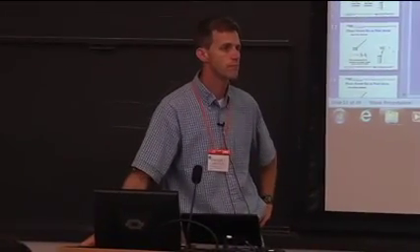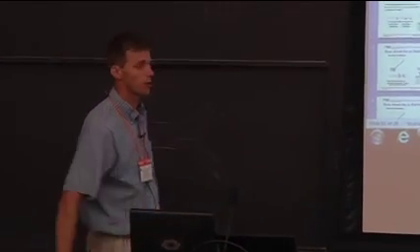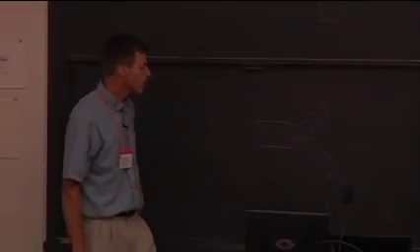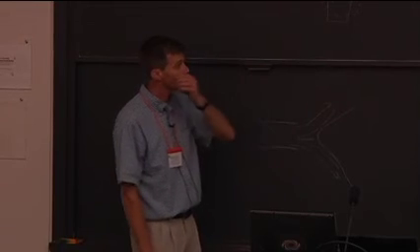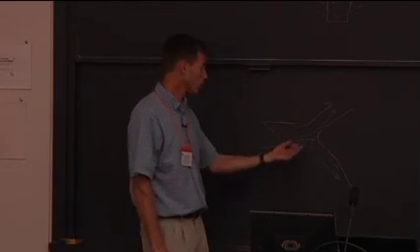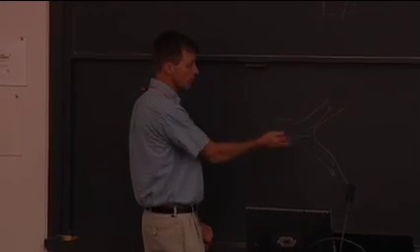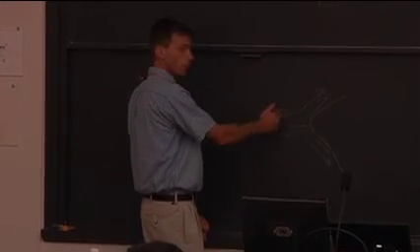But you may run into flashback at one point. Oh, sure. But any burner will run into flashback, I guess. But the beauty of this one is that whole combustion-induced vortex breakdown mechanism just totally goes away. But yes, there will be a velocity range where flow could flash back. But if you design it below criticality, then at least you know the flow won't break down in the nozzle.